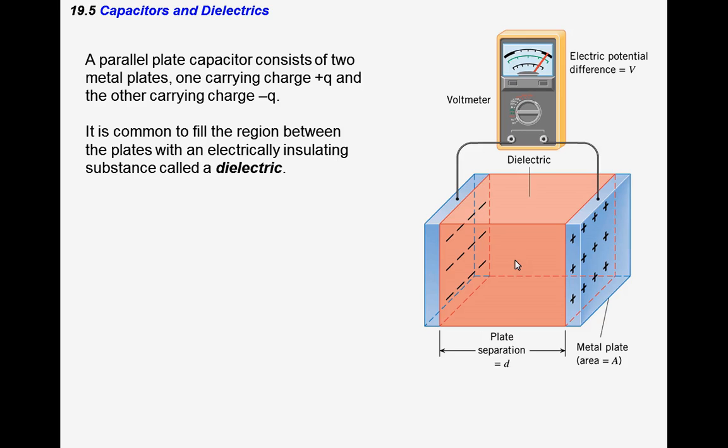So if I take 1.5 volt batteries and I stick them in a camera flash, if I just ran the 1.5 volts through a light bulb, it wouldn't glow very bright. But if I have a capacitor as part of that circuit, I can extract charge from my battery, and when you turn on a camera flash, if you've ever held one that's not your cell phone, you hear whee!